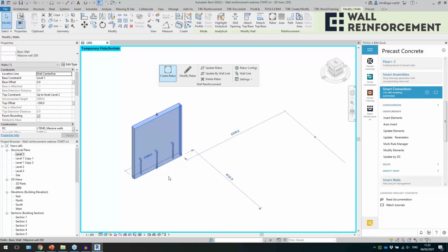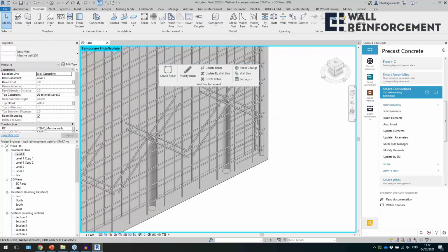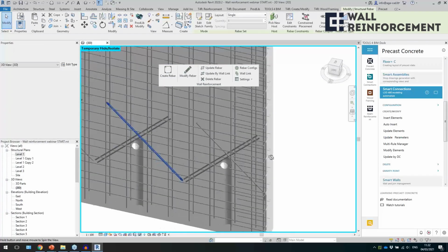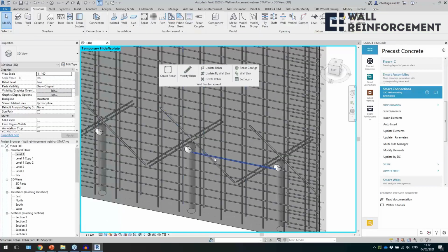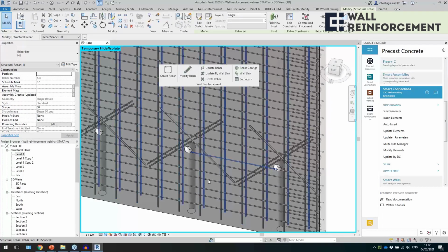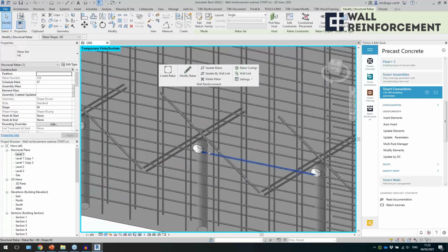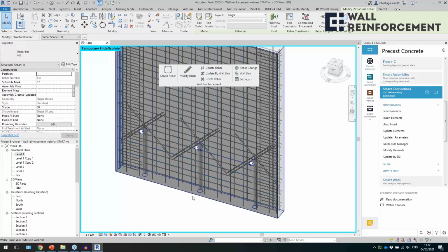So if I create rebars, you see I have cutouts for the grout tubes. And so the software, the result is even worse because it thought that this is an opening. So it placed diagonal bars. These are just cutouts, right? But actually on site, they would probably just move it a little bit lower, and then no problem here.